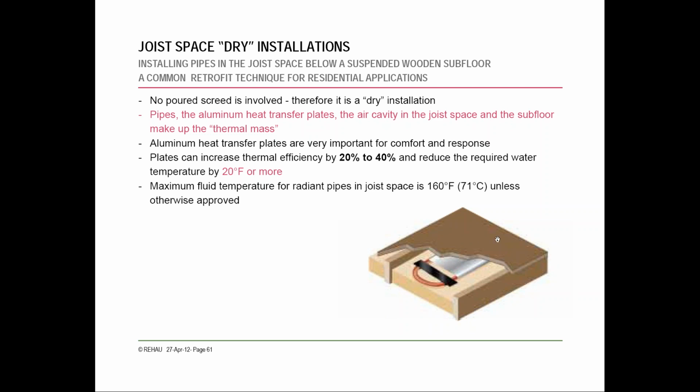This is another thing where different manufacturers have different heat transfer plates, different options. You could do this without heat transfer plates, but you're really limiting the amount of heat you can drive upwards through that wood flooring and then through whatever surface you're putting on top of it if you don't use a heat transfer plate. And insulation is even more required, mandatory, necessary with this type of technique, because you need to drive that heat up through, as I mentioned, the subfloor plus whatever you're putting on top of it. I believe the number Howe uses is you need to have at least 5 times the insulation below as the insulation value of the subfloor and the floor on top. But different manufacturers will give you different check figures there. You just want to make sure you're leaving a little air gap and then insulating below it.